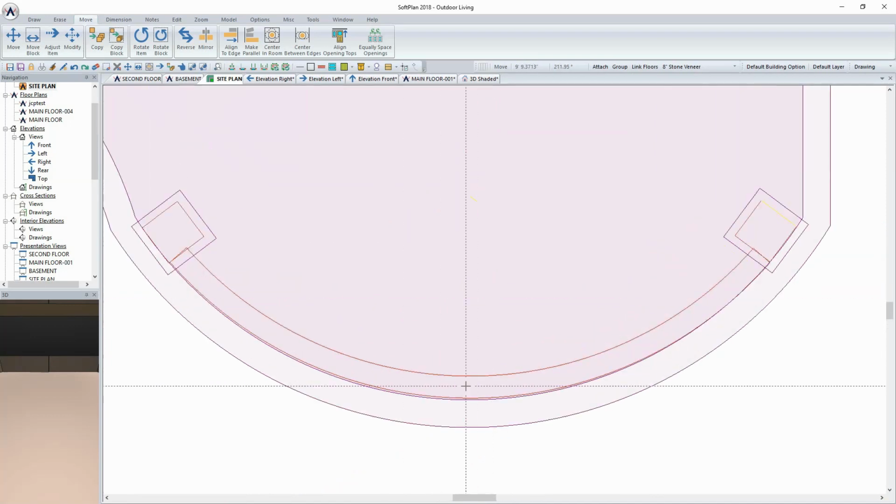The other thing that I could have done, which was part of the wall definition menu, was I could have just come in and edited this to have a capstone on top of the wall. The reason that I didn't do this here is this wall was actually drawn from this point and then drawn towards the upper right hand corner. And so while I could have given it an overhang on these two sides, running from lower left to upper right, the two ends would actually not have had an overhang on them because they would have just run the length of the wall. And that's why I went ahead and used the countertop.